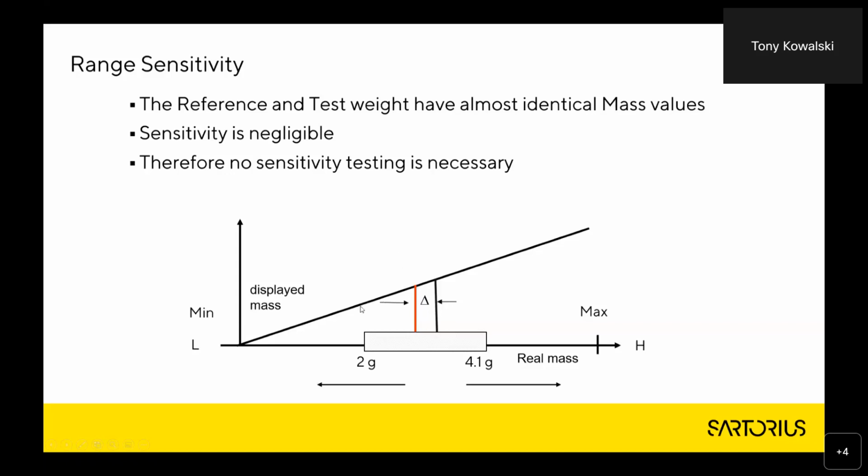because linearity is something that, once you've tested it, doesn't change throughout the life of the comparator or through the daily working of the comparator. Temperature change has no influence on linearity or range sensitivity, where it will have a difference on the absolute calibration. So it's not so critical to do a sensitivity test on a regular basis.